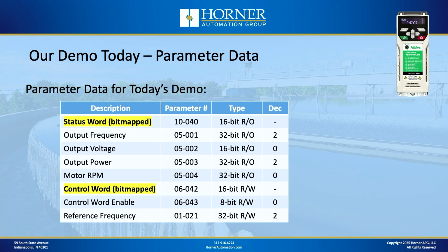And then on the other side, the control side, there's also a control word, which I've also got highlighted there, which is a bit-mapped group of bits that we can turn on and off individually to control the drive the way we want. And then in addition to that, for today's demonstration, I've also got some data I'm going to be monitoring on a read-only basis.